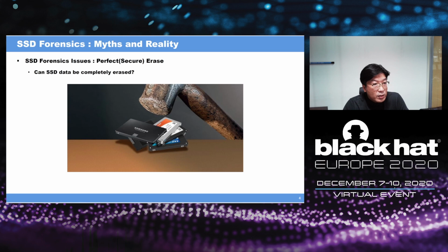destroy the information stored on all flash chips. Unlike software-based tools, the ATA Secure Erase command instructs the built-in SSD controller that supports the command to electronically erase all blocks on all flash chips in the drive.